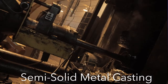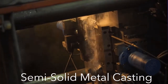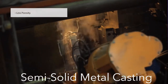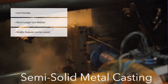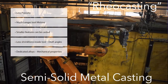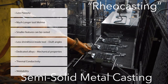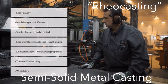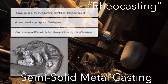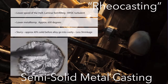The semi-solid metal casting. This casting process works with metal alloys at a temperature between liquidus and solidus. In this state, the alloy is a mixture of solid and molten metal during the casting, what is known as the mushy state. We need to keep the metal in this state for a longer time.